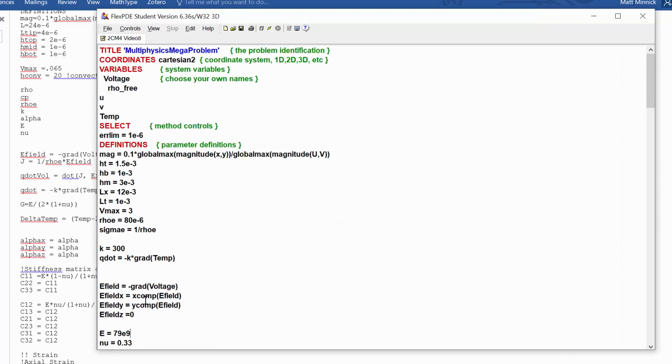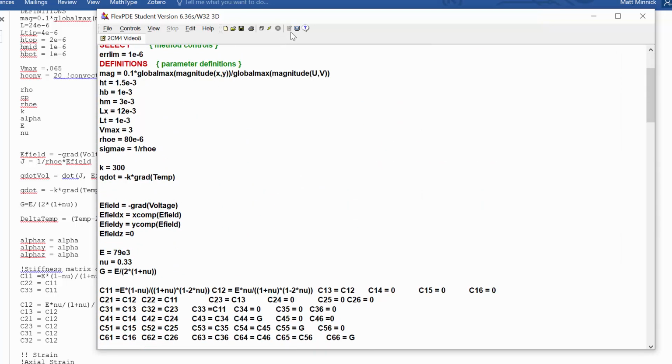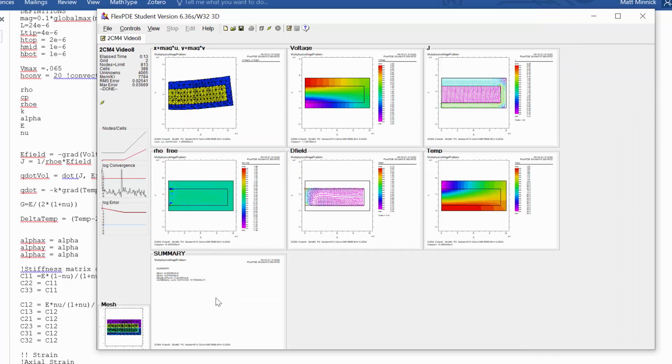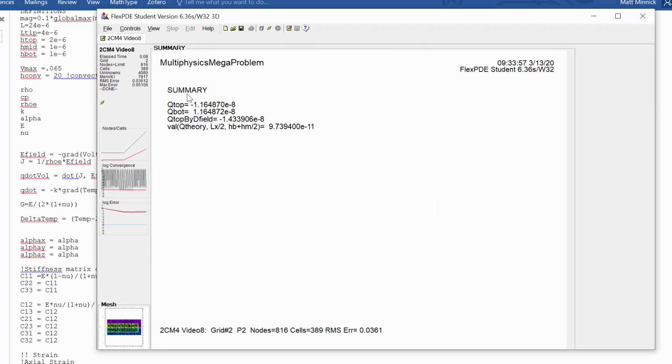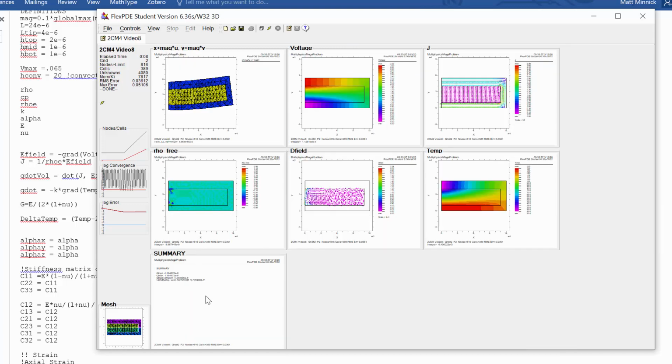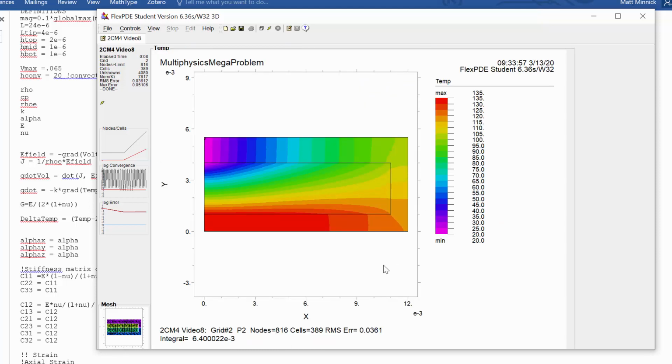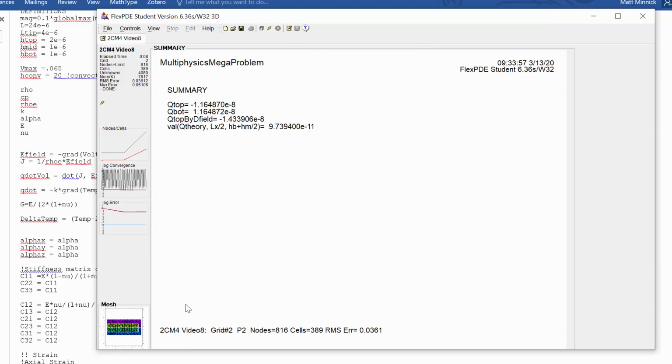If the metal is not very stiff at all, so more like 79E3, then this charge displacement that we're seeing will go down quite a lot. So now only about 1E-8, where a lot of that is not so much the thermal expansion itself, but, well, actually, I guess a lot of it's still to do with the thermal expansion, because the theoretical one is a lot lower. So if it wasn't for the piezoelectric effect and the thermal expansion showing up, we'd have a lot less of that actual displacement there.